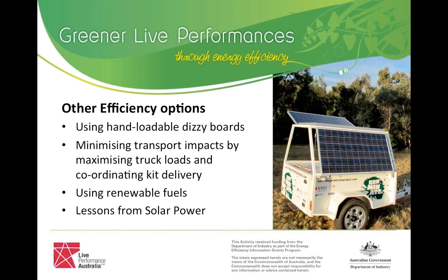So obviously, as you increase load, fuel burn goes up. As you decrease load, fuel burn goes down. So if you take your load off your generator at the end of the day and just let it sit there with nothing on it, there's a certain amount of fuel that will still be burnt just to keep that machine operating at 1500, but nowhere near what it would be under load conditions.